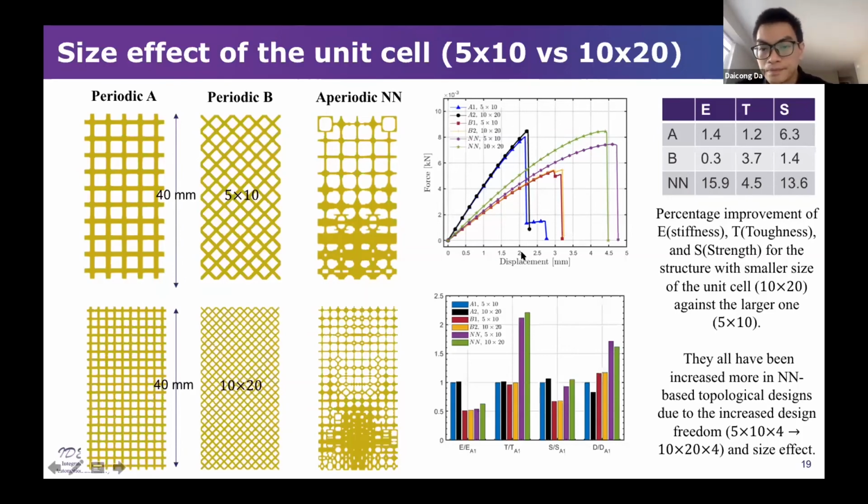And the other thing is the mesh. Because the geometry size is changed, the mesh when you do the fracture simulation is changed. But we analyze the mesh for a given structure and use a coarse mesh and a fine mesh. We observe that there's no mesh dependency.